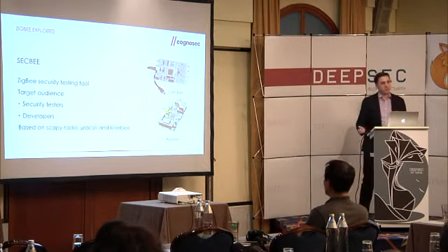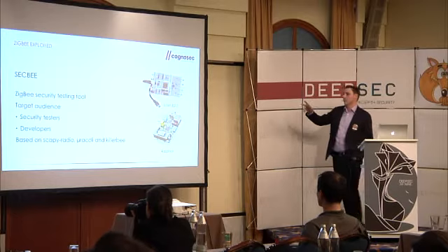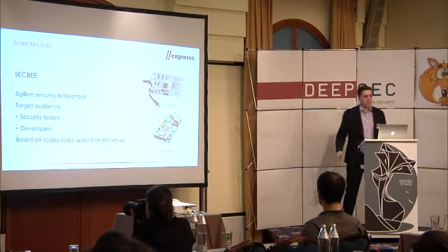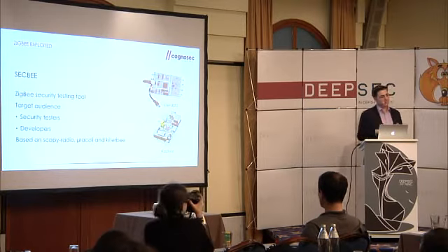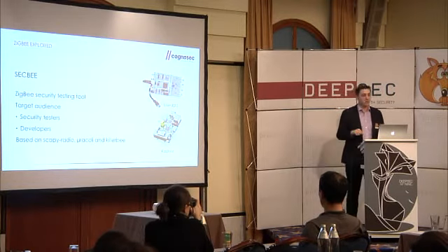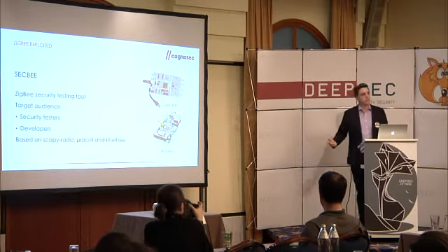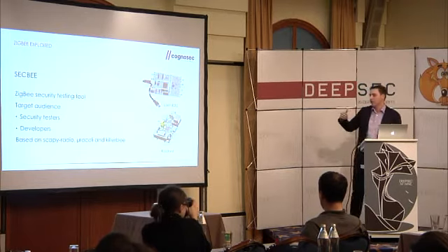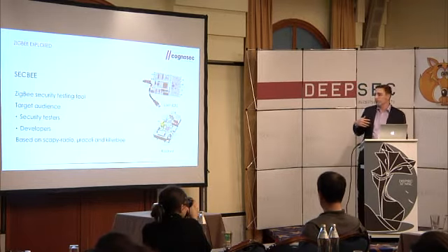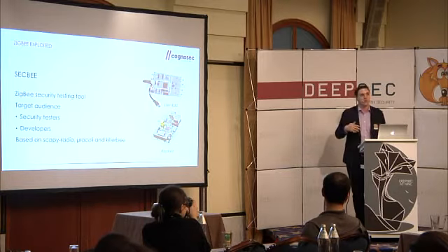We are using the USRP as software-defined radio, because it's a very powerful device, and we are also using the Raspberry Pi with an extension board called RaspBee for ZigBee communication. We will get to why we're using two devices there. On the software layer, the tool is based on ZigBee Radio and KillerBee and Miracoli. On top of that, we built our own functions. We implemented encryption, because encryption was not available or not integrated in KillerBee. And we noticed all modern ZigBee implementations are using encrypted communication.